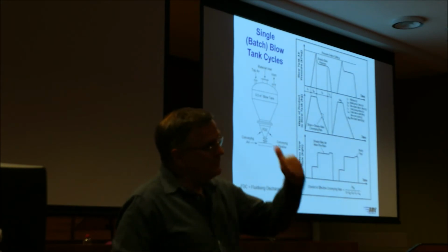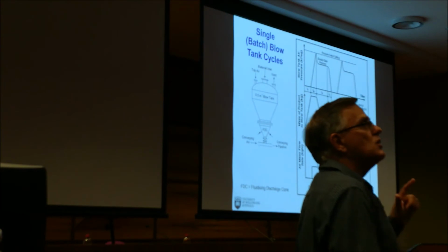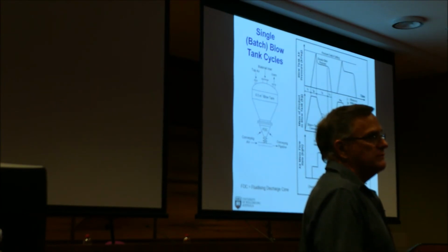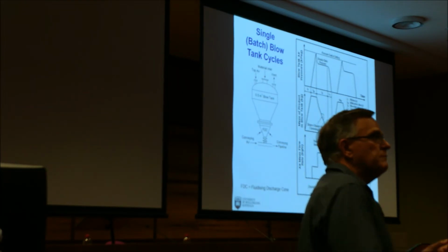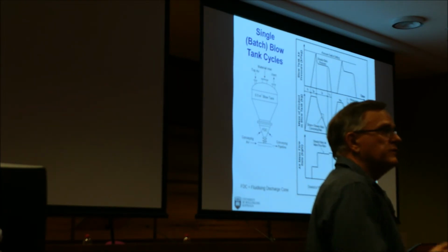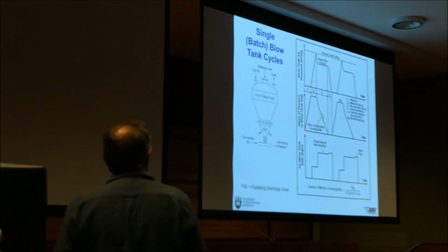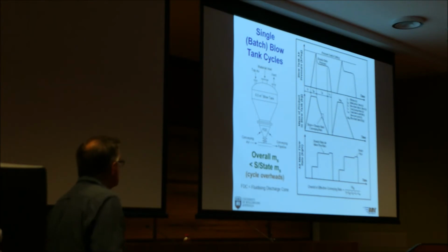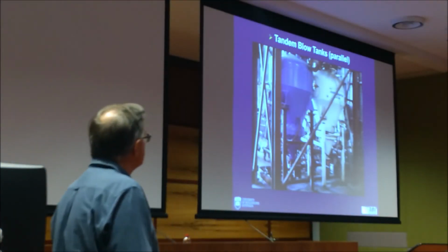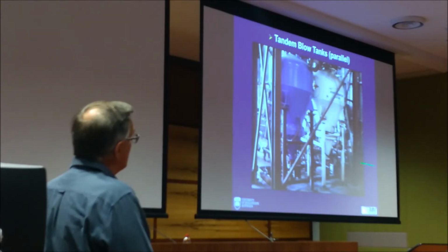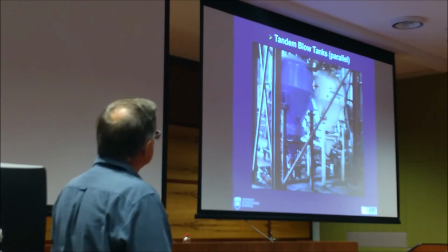So for large capacity and or long distance systems, we generally don't use one blow tank. We generally use two. Because you want to keep your pipeline full of product with large capacity and or long distance systems. So for those applications, we need two blow tanks. So for these, this is our old test rig in Wollongong. We ran up to 1.2 kilometres.